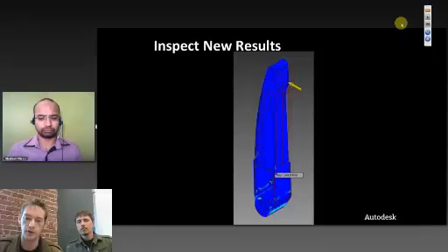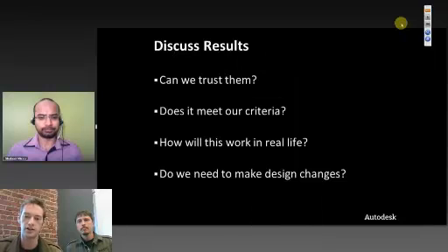Here we are. So now we have a maximum stress at about 150 megapascals. And I know that that's a factor of safety of about 1.8. And on the next slide, we can discuss what these results mean. The question is, well, is a factor of safety of 1.8 acceptable?